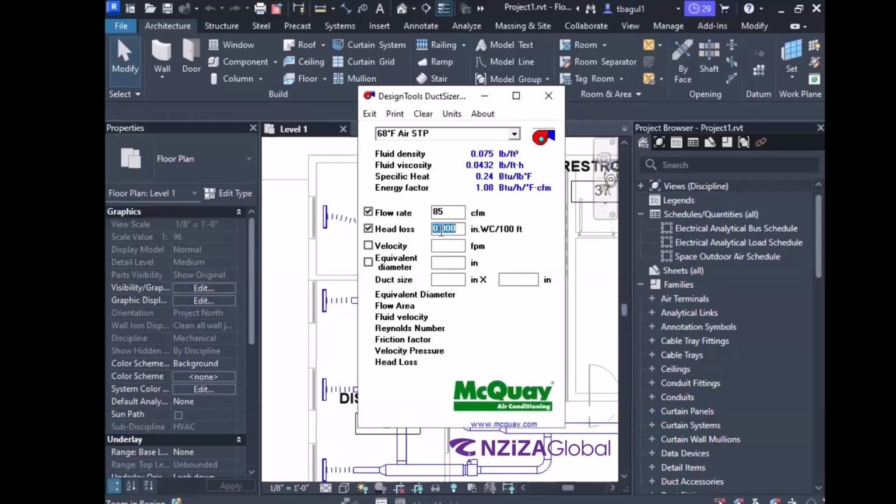There is friction between the fluid, in this case water, and the surface of that pipe, correct? It slows down the velocity of the water, slows down the pressure of the water. Make sense? So the same thing is happening over here. How much pressure drop we are getting with respect to 100-foot length of duct.